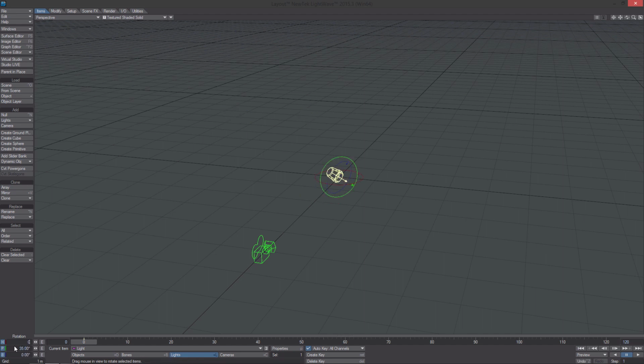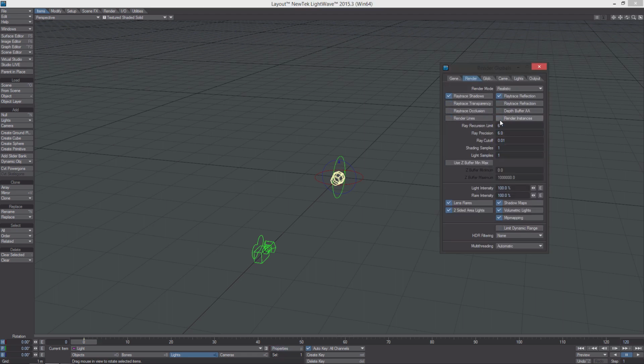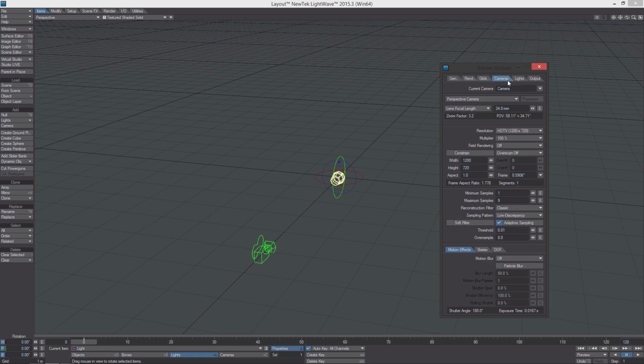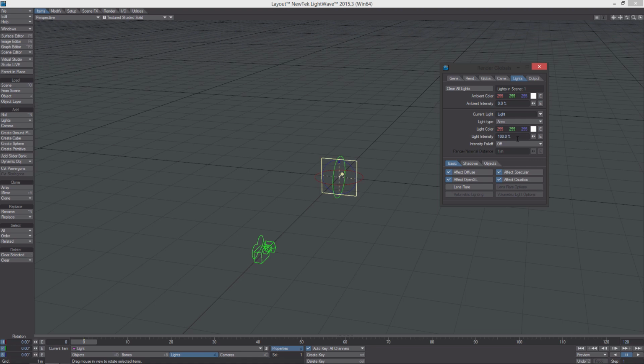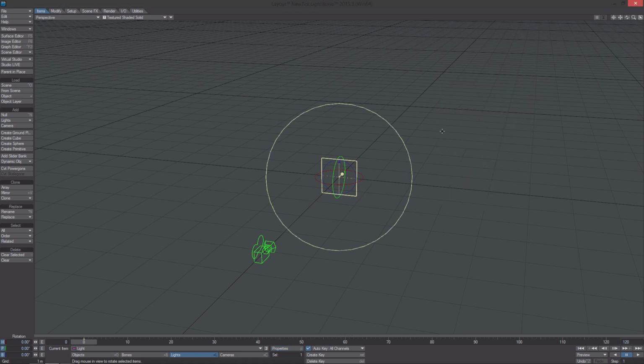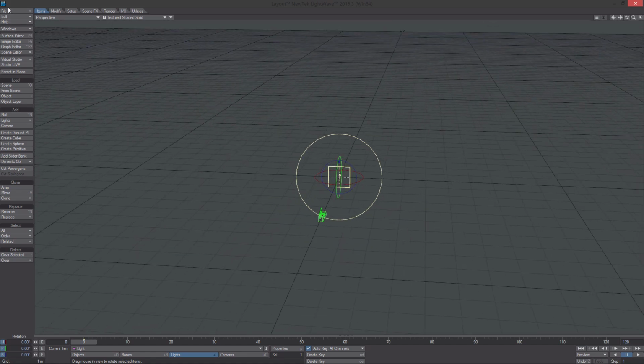Now all I'm doing here is zeroing out the position and rotation for this light. I'm going to create an area light out of it. Just changing these settings. You don't want double-sided area lights. That will mess this up, so make sure that's off. Turning the ambient down, I'm making it an area light. Turn it on inverse distance squared clamped. Falloff at 2 meters.